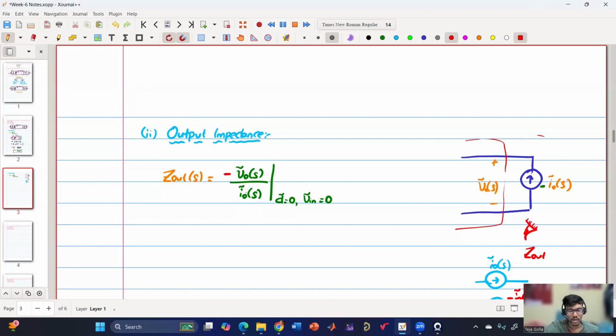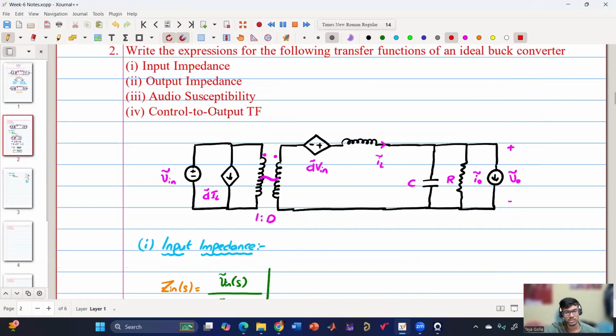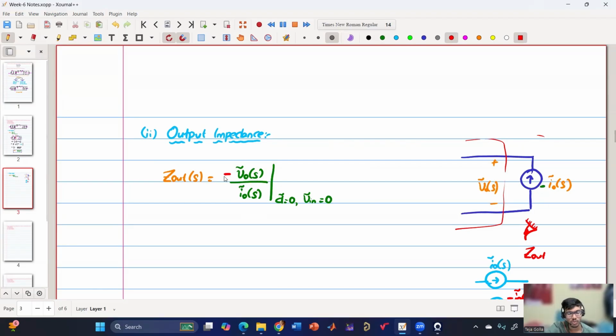So this is somewhat tricky and where people make mistakes, so that's why I'm stressing here. Our I naught should have been a source, because whenever we are exciting something, you should supply current to that something, say here the converter, and then you have to see the response, which is V naught. So you have to supply the current to the circuit, but instead you are drawing the current. So if we are drawing I naught tilde, it means we are supplying minus I naught tilde. So that's why we will have a minus over here. Is that clear?